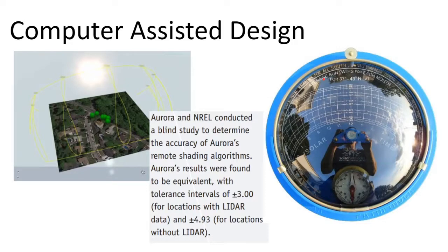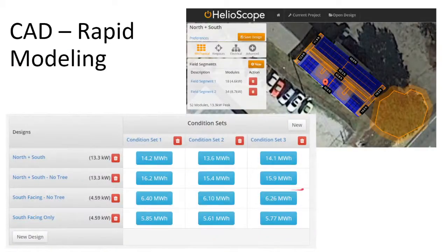for shade analysis. Now, a detailed shade analysis done in a computer environment would actually be calculating the energy on the solar array at every hour of the day and giving it to you in a very detailed, granular report. The most accurate shade analysis softwares are found to be as accurate as going to site and doing a shade analysis. I actually think they're more accurate because, again, trees grow over time, and so modeling the tree growth is better done in a 3D environment than a 2D environment.